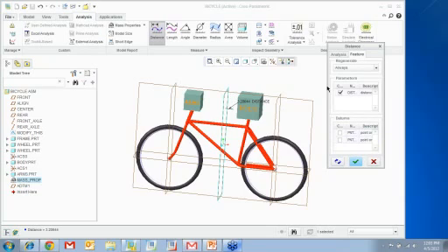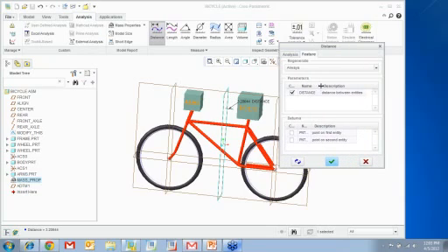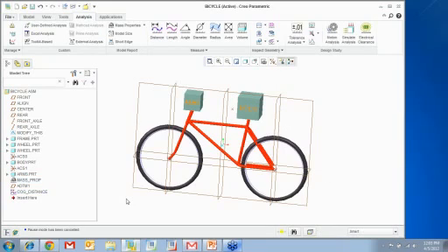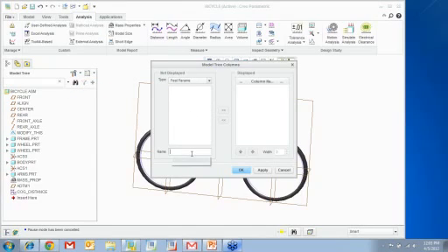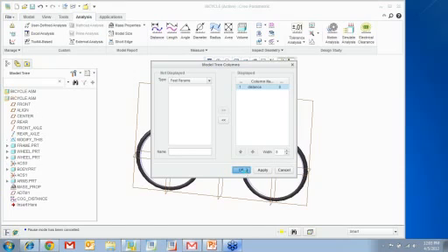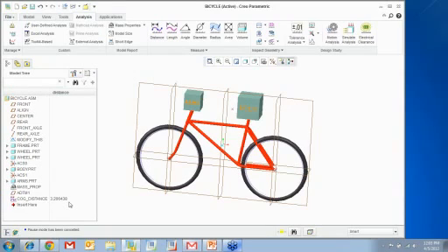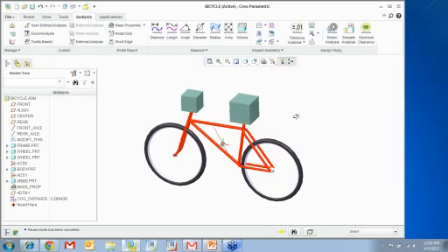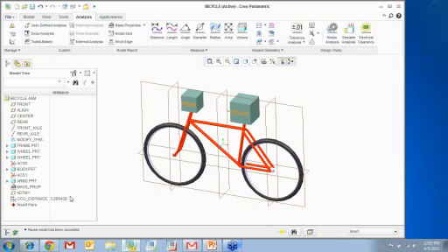Alright. You should also see that it will create a distance parameter for you. So if you want to know what the current distance is, you would go here to columns, feature parameters, and just type in distance. This is the name of the parameter that we want. So it will show you what the value is between that point and the plane. Anyhow, our idea is to minimize this particular distance to be 0.